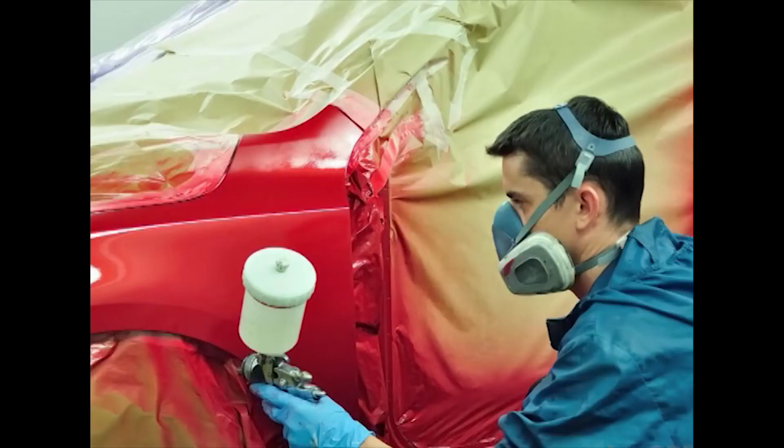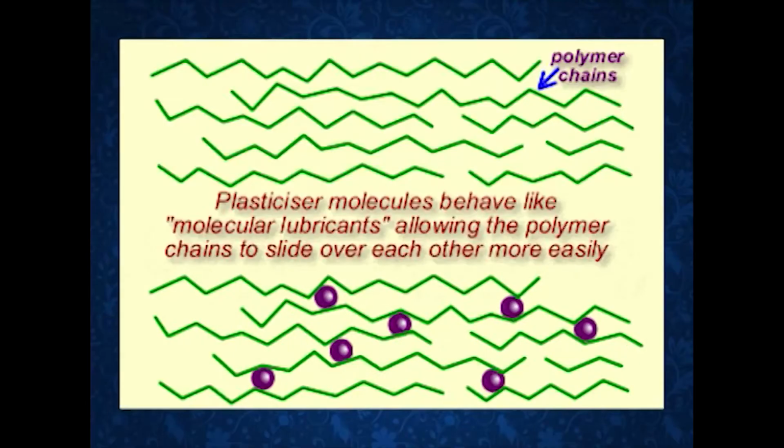Evaporation rate is one of the most important parameters, as the solid outer coating is formed because of the evaporation of the solvent from the surface. Other characteristic properties comprise the ability of the paint ingredients to dissolve and its toxicity. Additives are small amounts of substances which modify the properties of paint, for example, dryers, plasticizers and emulsifiers.